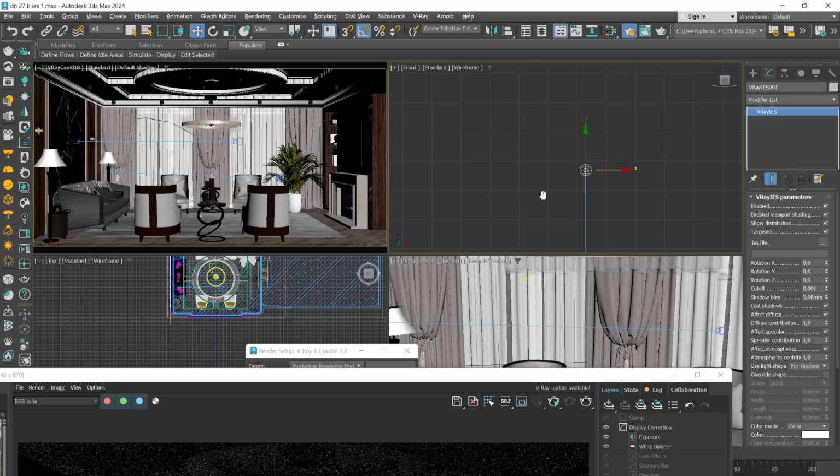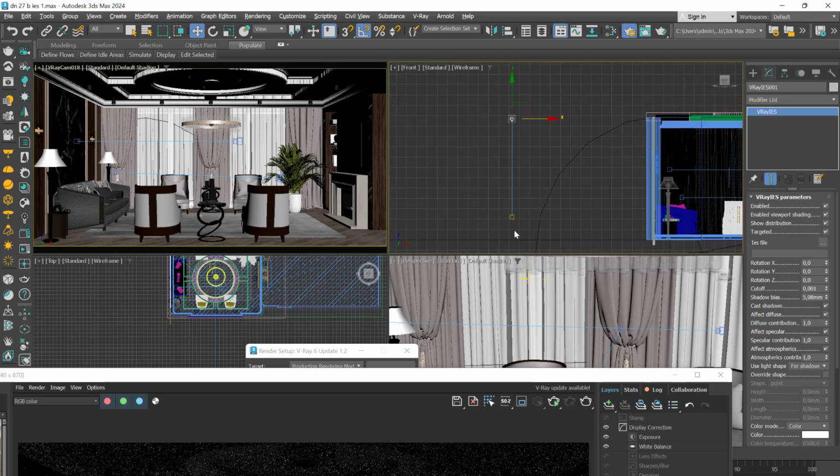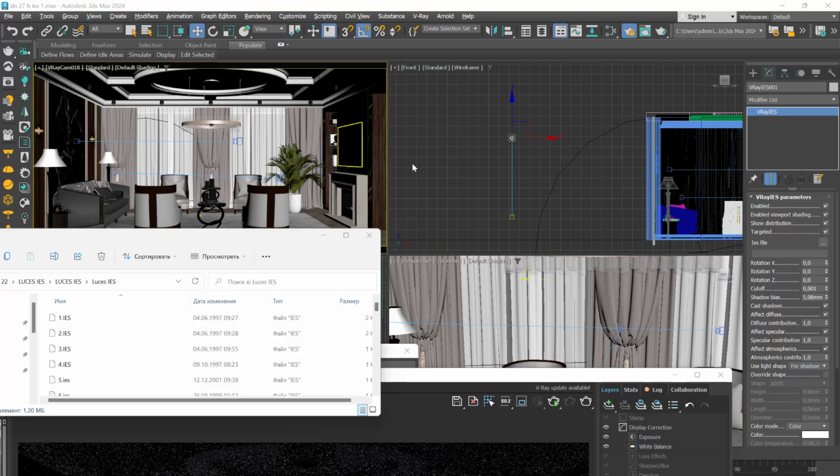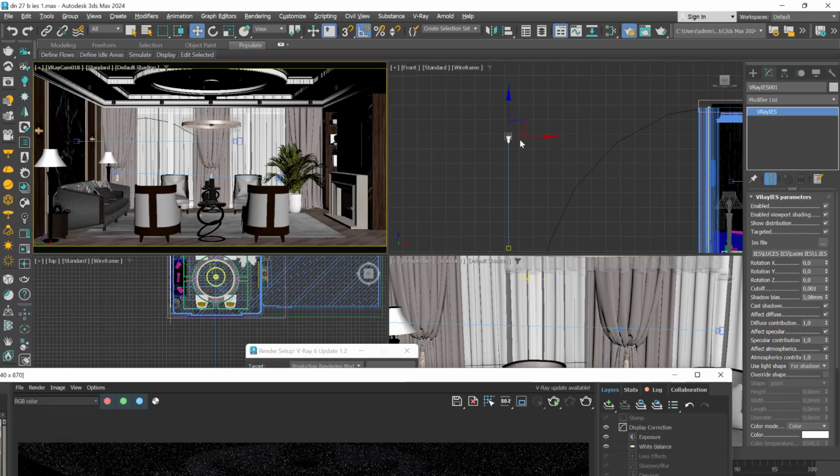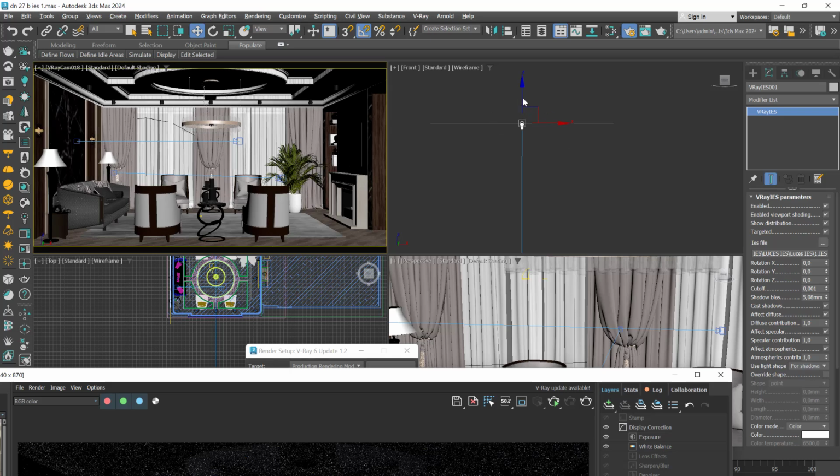Next, our light source got a target, and we usually create this type of light, as I said, straight. Let me lower our Vray IES a bit, and we will install this light under our light source. Next, we will go to our Vray IES library, pick the first one, and load it here in the profile of our Vray IES. Now our Vray light source changed, and you can see here the profile applied. And now this light will repeat the same light distribution like you saw in the image.